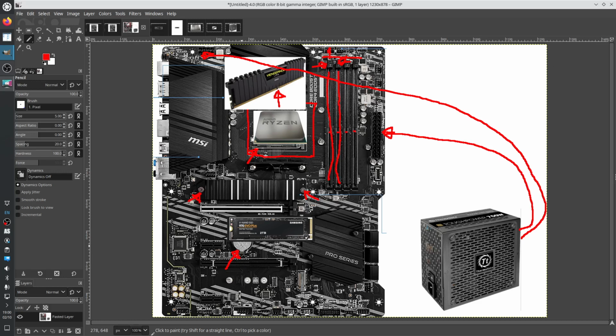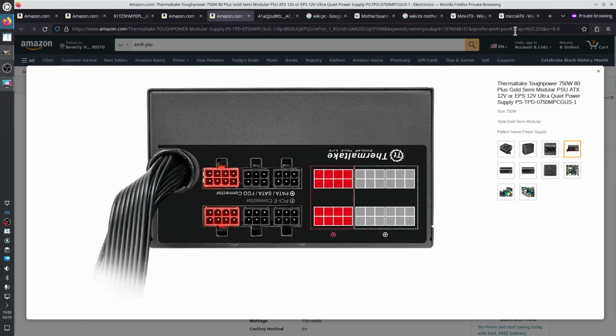And this thing is connected to a small circuit that contains what's called the basic input-output system, or the UEFI. So that's the first thing that the motherboard powers on. And then that thing and the CPU decide that there exists a RAM in one of these slots, test that the RAM is okay, train the RAM, and then it can show the user interface for the UEFI BIOS, which looks like this.